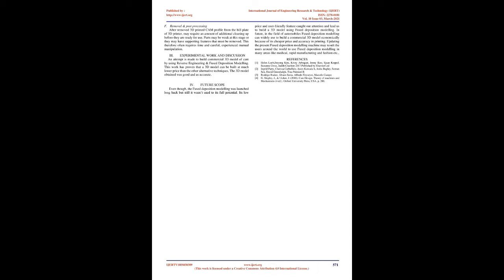The hollow object can be partially filled by internal structures, such as internal walls, to provide additional robustness. The amount of these structures is called infill density, this parameter being one of the adjustments to be provided to the slicer. Supports. Most of the 3D printing processes create the object layer by layer, from down to up, with the layer under construction being deposited over the previous one.